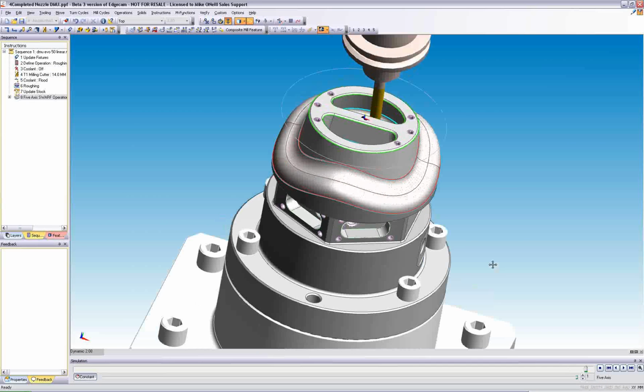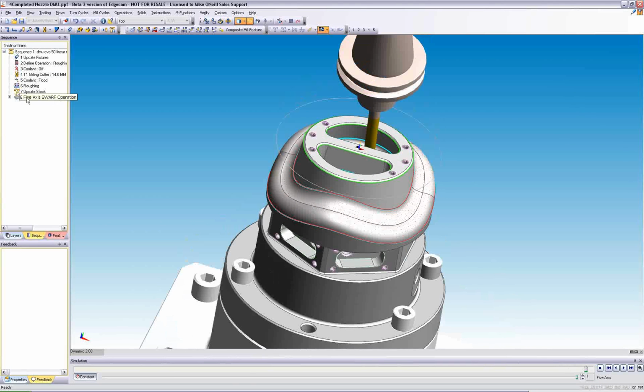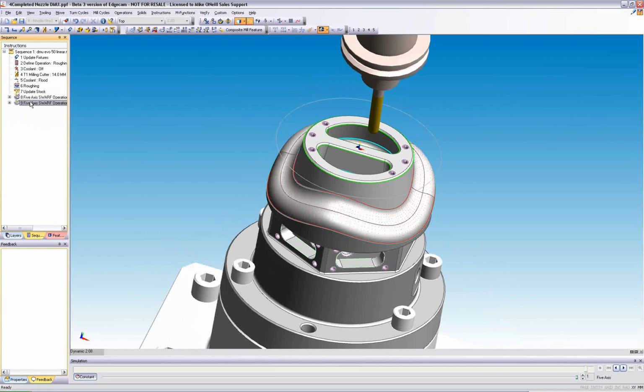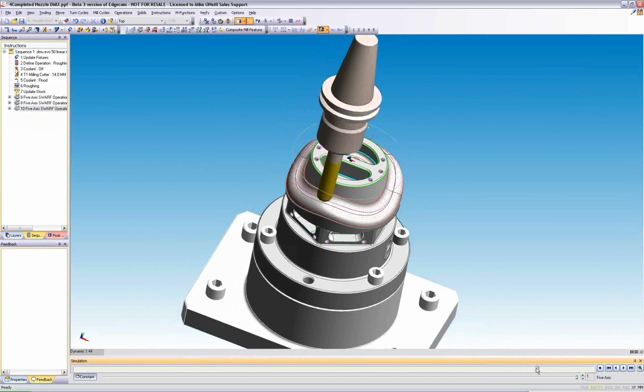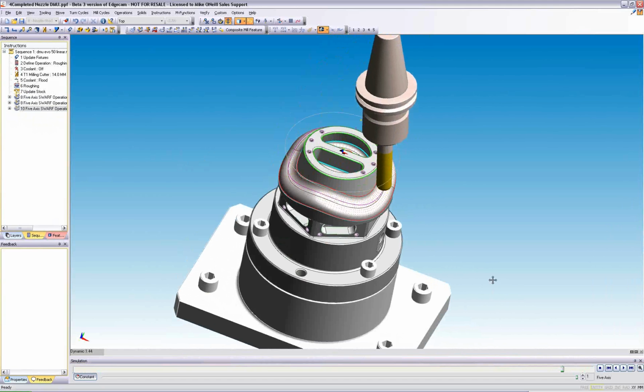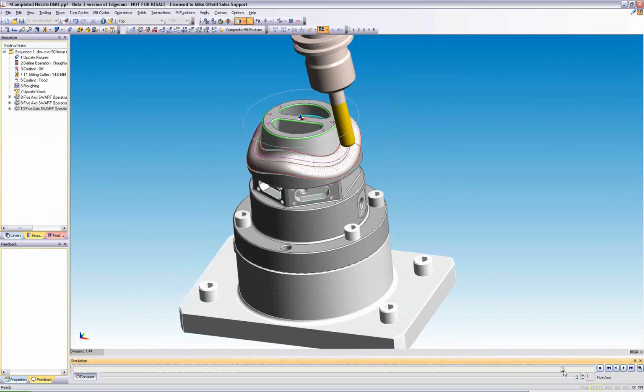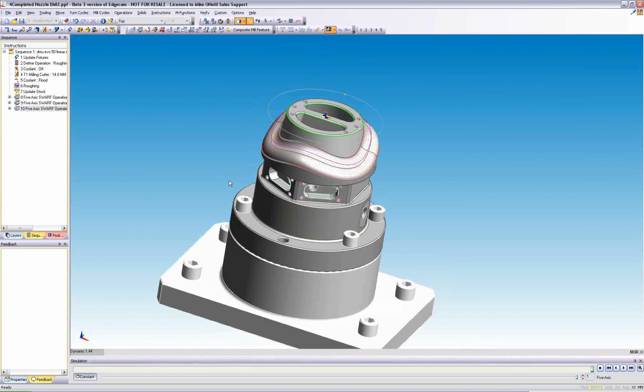Notice how the tool will now machine tapering inwards to the sidewall, and the toolpath, knowing that it's already been produced and is safe and gouge free, is copied down, and the machining toolpath is transferred to the opposite feature. A third swarf operation is also created. This again, as you can see, leans the flank of the cutter into the component.